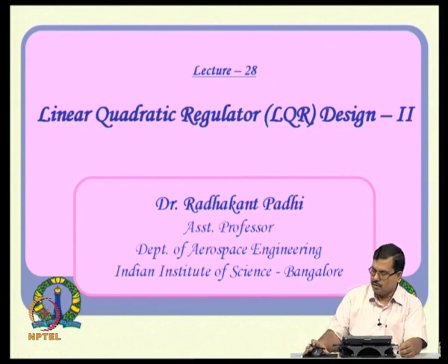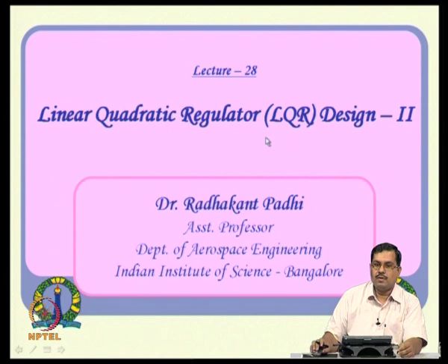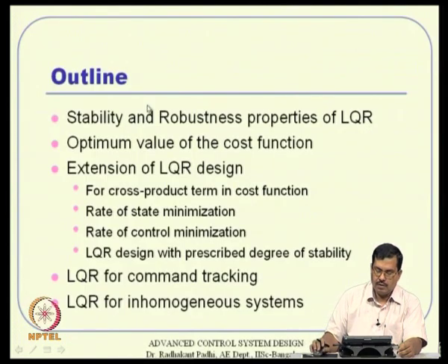There are many things that we can discuss under the LQR design, and we will cover some of the important things associated with design. So, the outline of this lecture will be like this. We will first study the stability and robustness properties of LQR, and we can also see the optimum value of the cost function directly in terms of the LQR solution, the Riccati equation solution.